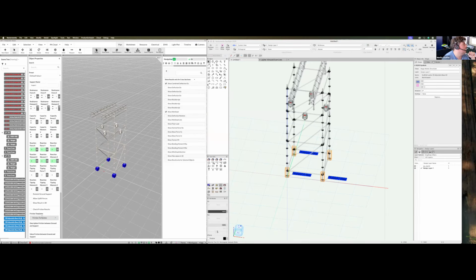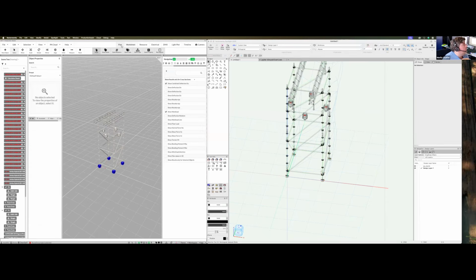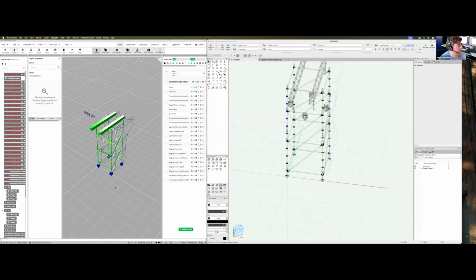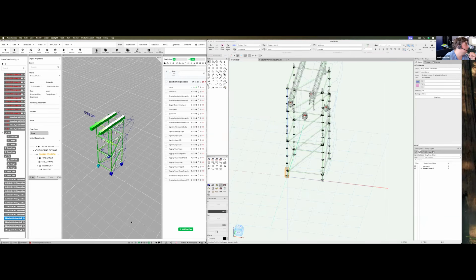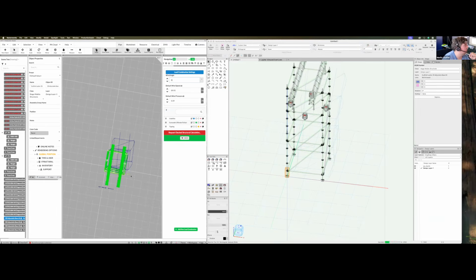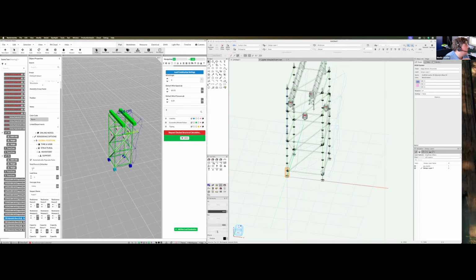So the easiest way, what I normally do, is a trick: allow the uplift forces on this. Allow uplift forces basically allows it to have negative forces in here. So when you click on this, wait, let us quickly go into another thing with this, like 0 degree, so that we have one thing in here. So it will tip over in this direction. And if we do look into this in here, you can go to the support and it has a negative force of 1.34 kilonewton in here. So there is already a negative force in here.